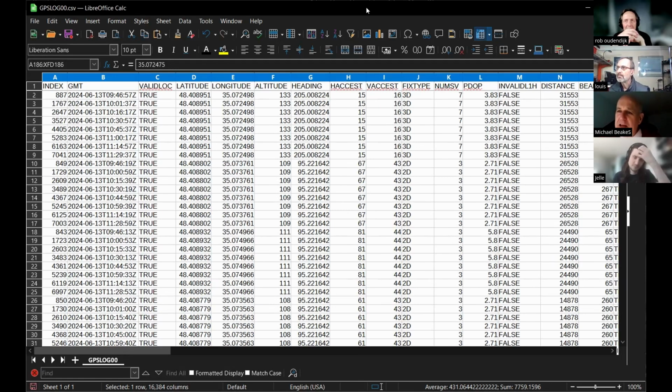Yes, and you need a cable between the two Zens with ground, TX and RX, and the cable has to swap TX and RX between the two units. Okay. So in other words, it's not just replaying it from the SD card. It's actually reading it as if it was receiving it from the u-blox module. Right. Okay.